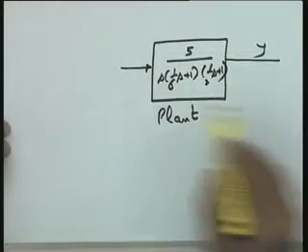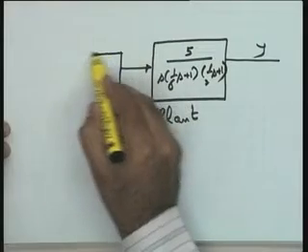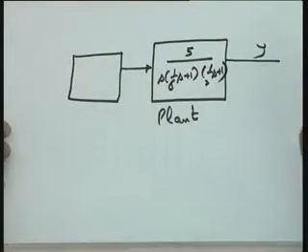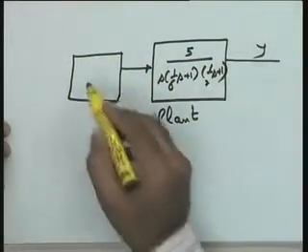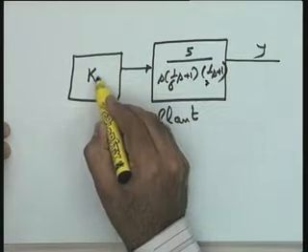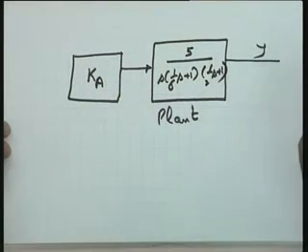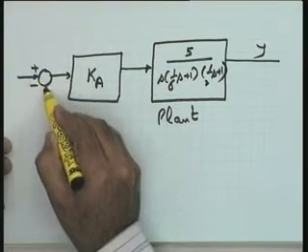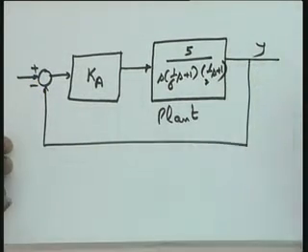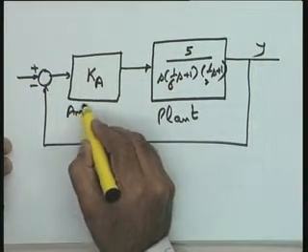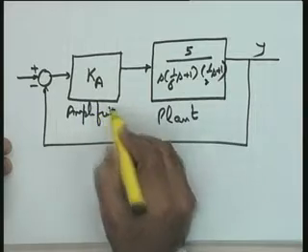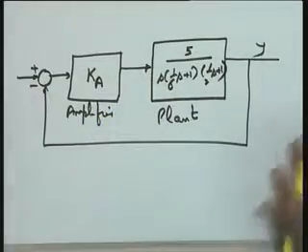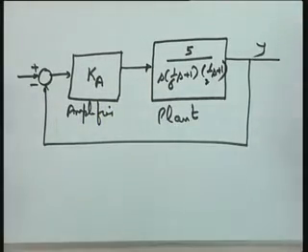Naturally, in any design problem, whatever may be the performance requirements, you will first of all like to examine whether by pure gain adjustments your requirements of performance are satisfied or not. So, the very first diagram I like to examine is this system diagram, where this amplifier is a simple proportional controller. I like to see whether Ka satisfies this requirement or not.